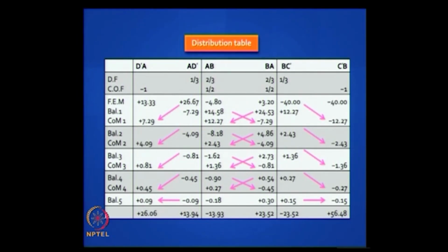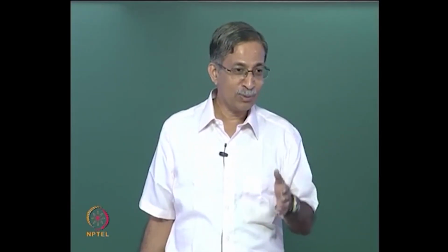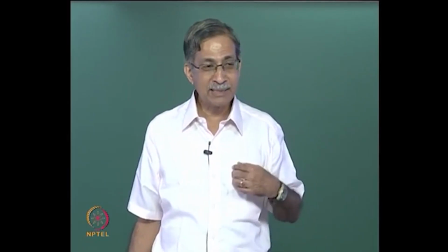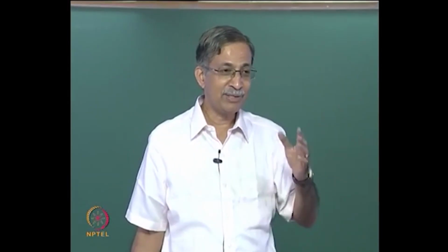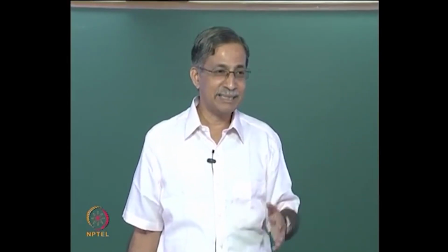Sorry? Soil pressure when it acts on a retaining wall. Have you gone through a geotechnical course? You are going through. So you will know that if it is water, it is hydrostatic. If it is water, Pascal's law says that the pressure is the same in all directions. If it is soil, it is not the same.